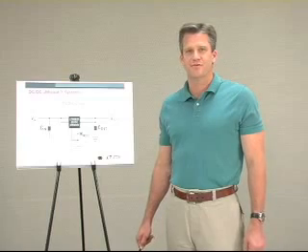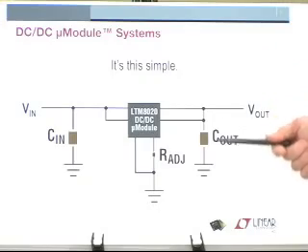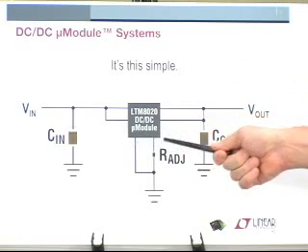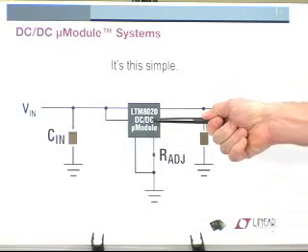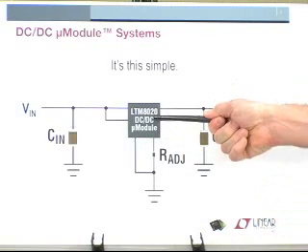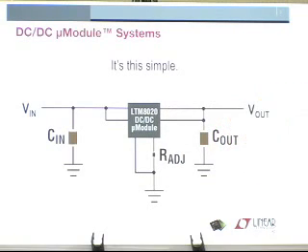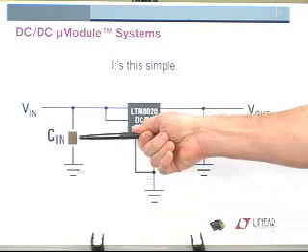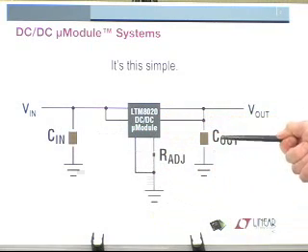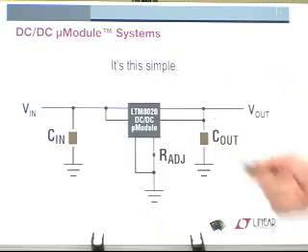Let's look at a simple design example. In this simple design, we can see a fully integrated package combining all of the complex regulator circuitry and the simplicity of use of a linear regulator design. As you can see, this design requires just one input cap, an output capacitor, and a programming resistor, which is very similar to a simple linear regulator solution.